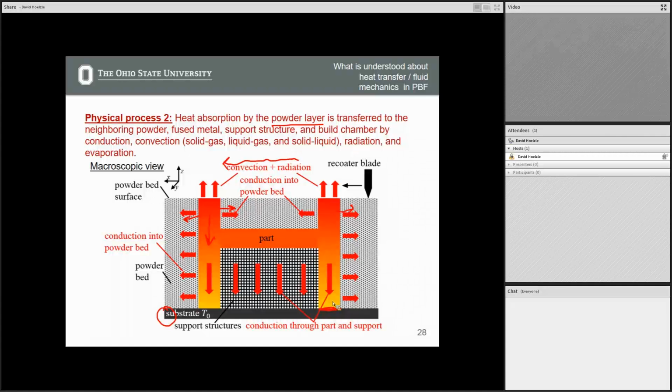Okay, so electrode discharge machining, not electronic dance music, is a mechanism in which you put a high current through either a wire or some sort of part, and then you have the part itself grounded, and then you have a certain type of fluid in between, and you're actually eating away that part surface. This is probably all scripted physics of it, but basically you're creating a charge between those two surfaces. You get a lot of current running through it that actually eats away the part surface in a very slow manner, but also very precise.